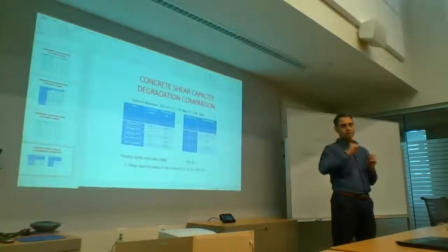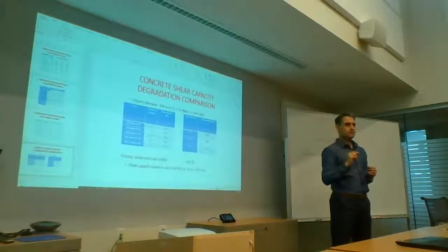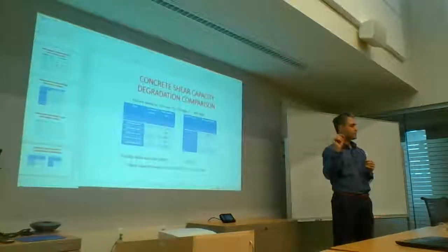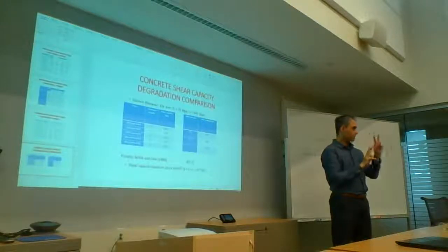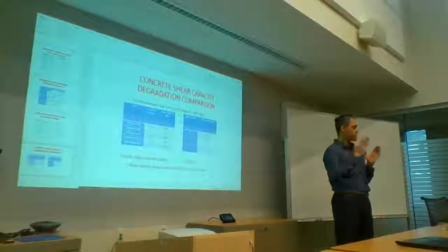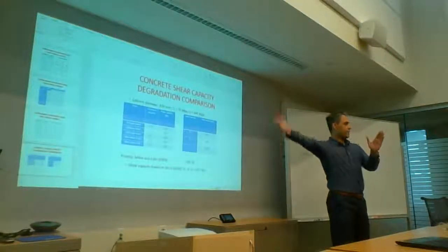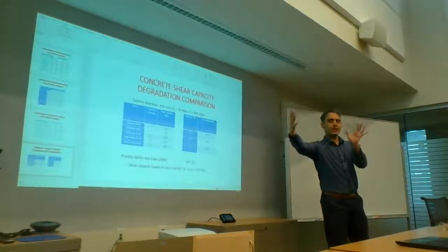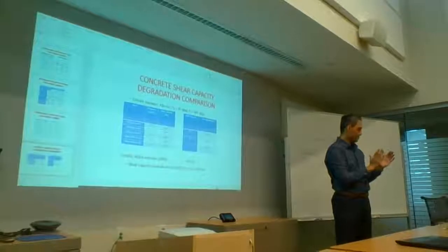And now compare that to extensive, which is what 2475 is tied to. The rebar allowable strain is 0.05. So for an increase in seismic demand of a factor of 2, the capacity increase that you're allowing is 25 times. So for an increase of 2 and a capacity increase of 25, that's never going to be your governing criterion. It's always going to be the first one.